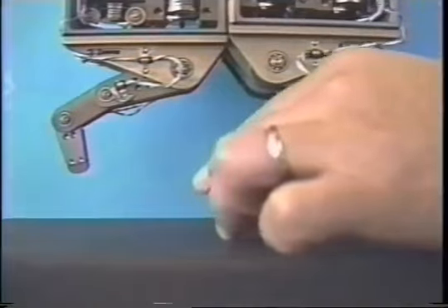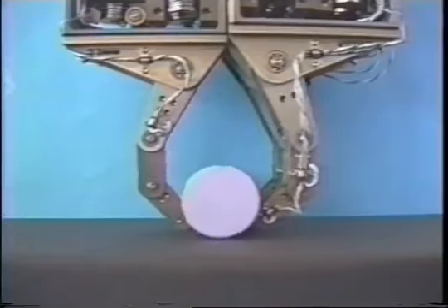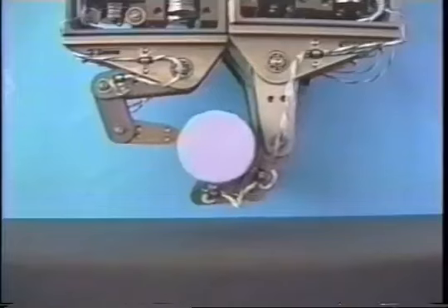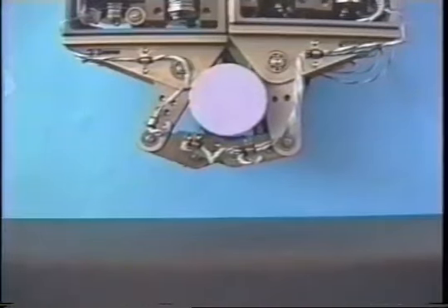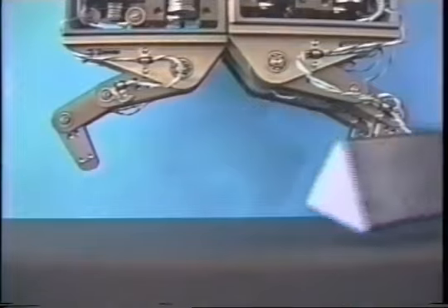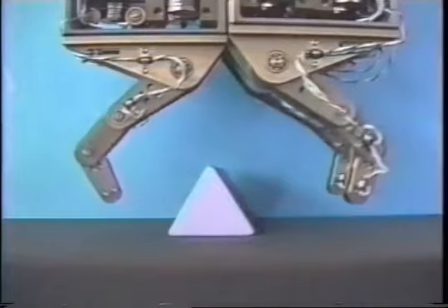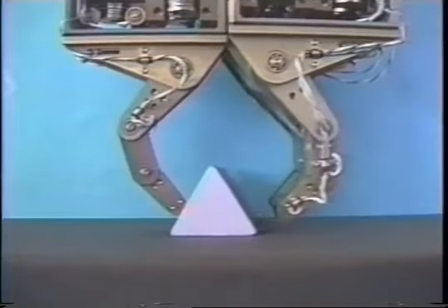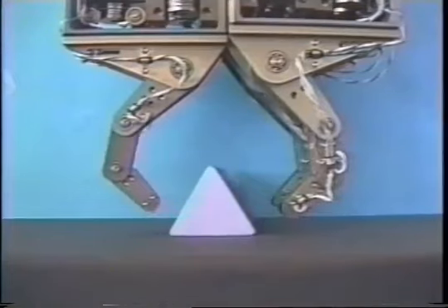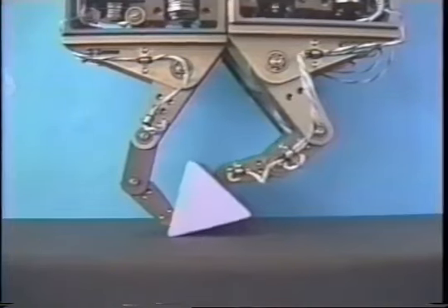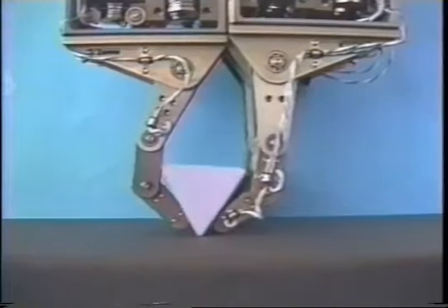This cylindrical object is covered by a rubber coating so that we purposely increase the contact friction. Under such significant friction, the wedge effect-based approach does not work anymore because the slipping motion between the link surface and the object cannot be produced. To cope with this situation, we execute the lifting motion by rolling, as shown in this experiment. The robot finger adaptively switches its strategy into the most appropriate one based on the joint torque sensor information during the grasping task.